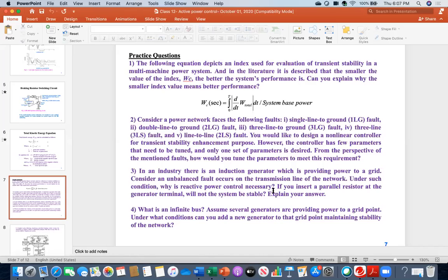Exactly, right. So everybody see in the very first line, your generator is induction generator. That is not the synchronous machine. Because you have the induction generator, continuously it is taking reactive power from the grid, as Manoj explained, to produce magnetization. And that is causing the low lagging power factor. So that is even the normal situation during balanced case, during stable situation. So it is continuously drawing the reactive power for its operation, and then the fault happened.